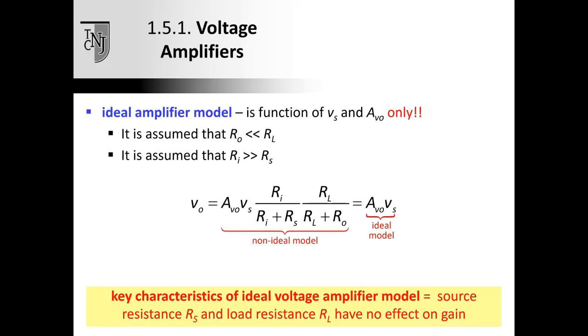Over here, our RO, let's say that's 100 ohms. Then our RL better be at least 10,000 ohms, 100 times larger than that. Now, this is not just some textbook question.